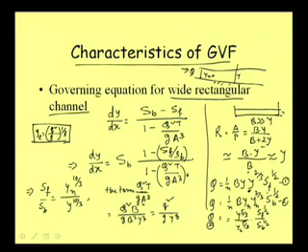So, based on that, starting from that, this is for a rectangular channel of course, and we are talking about a wide rectangular channel, the same thing. So, q square by g to the power 1/3, that means yc, here we have q square by g. So, q square by g is nothing but yc cube. Well, so this we can write as yc cube by y cube.